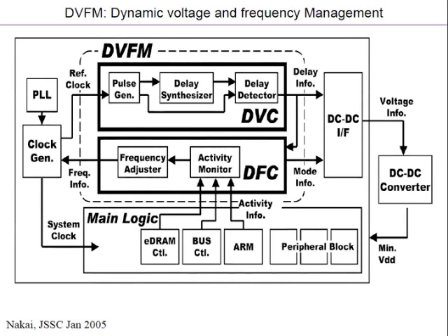I'm just throwing out the number 100,000. It could be maybe 1,000. It depends on the system level configuration. In that window of time, you observe and count the number of times you have accessed the various resources. If the number of accesses is very small, you can say I don't need to run that fast. Not much is happening. If it's very large, then you know that a lot of things are happening. So based on that, you can adjust the frequency.